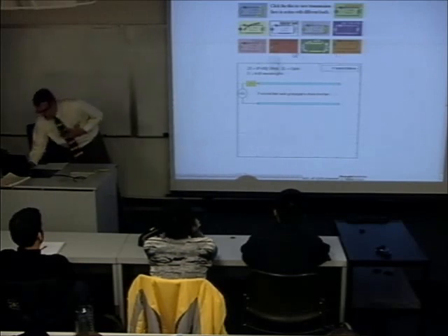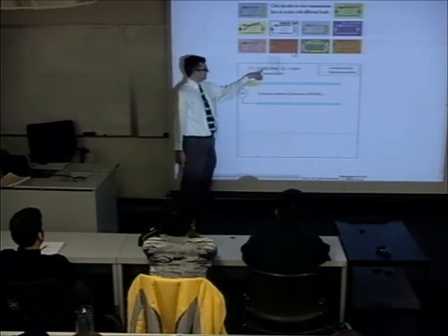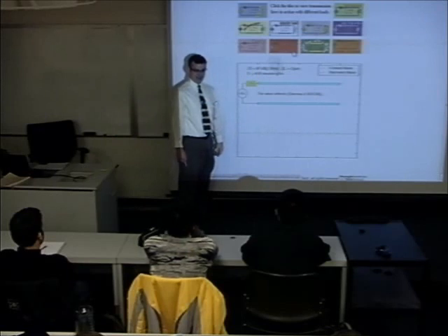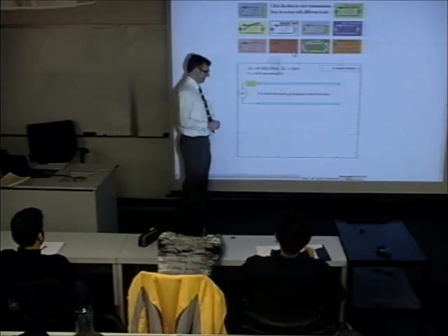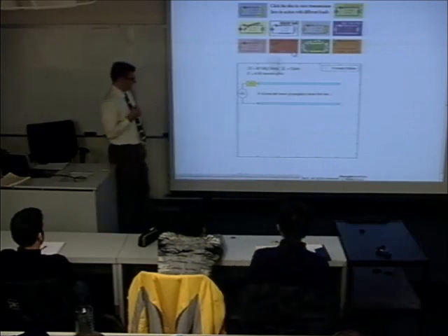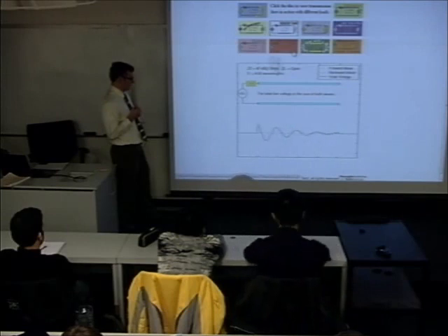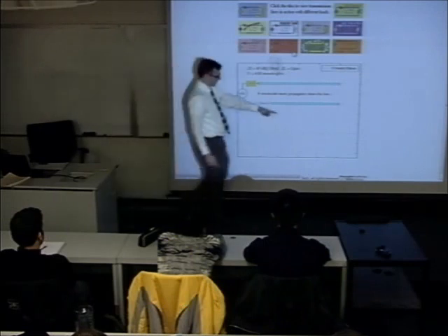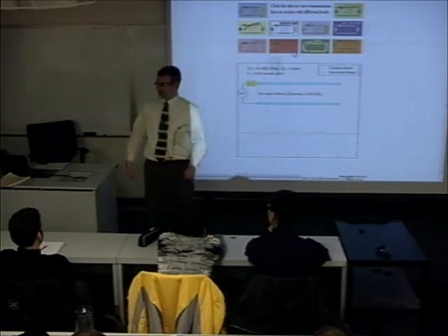Let's see, here's a high loss line. Open circuited, but Z0 of 67 plus j30. So it's mismatched, but also notice that it's complex. We'll see by the end of class, hopefully, that complex lines also indicate that there is loss on that line. We'll explain why. Yeah, there it is. Very sharply attenuating exponential in the total envelope. It looks like a very sharp exponential with a little bit of ripple at the end. But one nice thing about high loss lines, you don't usually have to worry about VSWR on them because the signal dies out too fast.